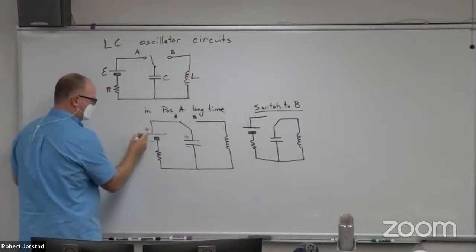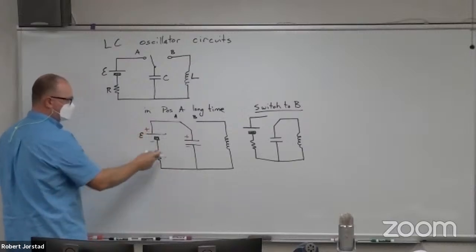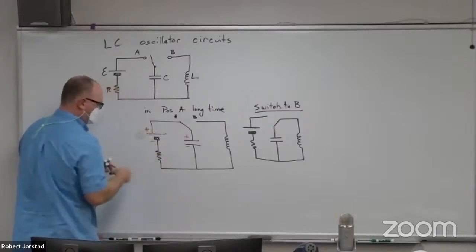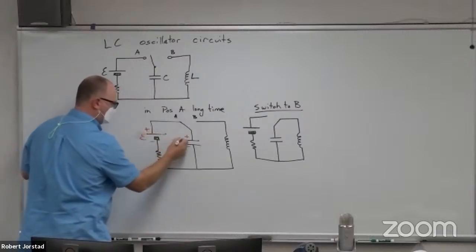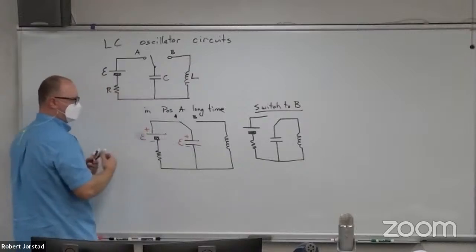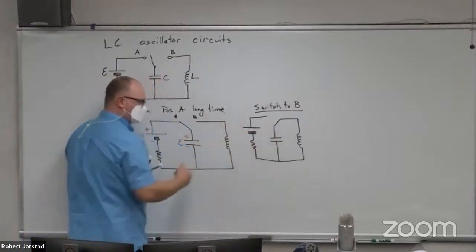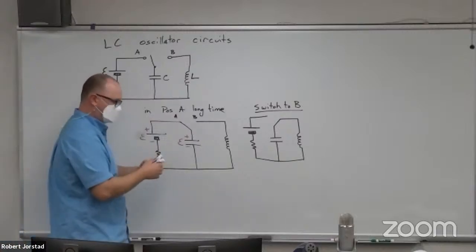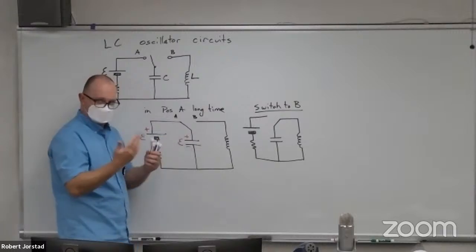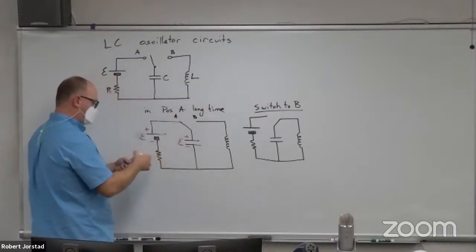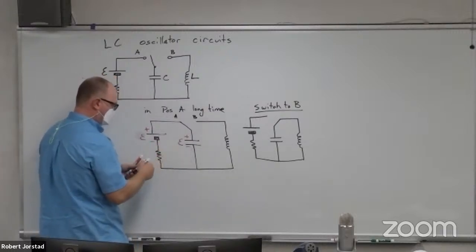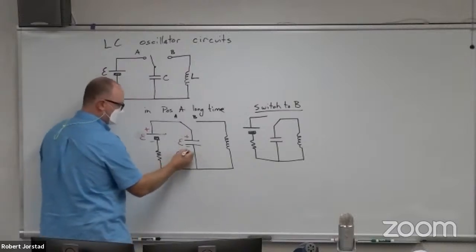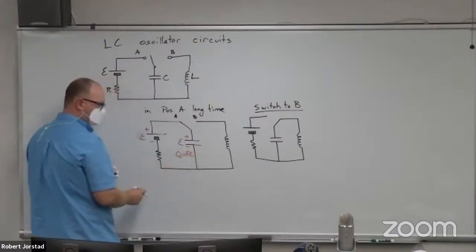Okay? So if this voltage right here is E, what should be the voltage across the capacitor? E. Does that make sense? I bring that up for what reason? What does a capacitor preserve when you change the switch? Charge, okay, or voltage. Charge and voltage are the same. Let me ask you this. What's the initial charge on here? It's EC. Right? So we know the charge.